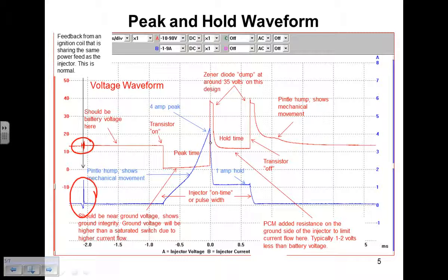When that can be crazy is at higher RPMs, and when you're looking at multiple waveforms, sometimes this spike can end up being inside of this pattern, depending on RPM. And if you're looking at all of them or only one of them, and man, can that throw you off, because now you've got this weird waveform within your waveform.